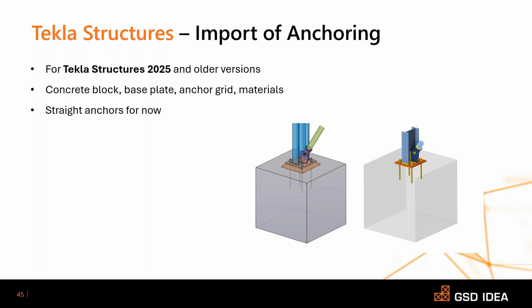Now with the base plate, you can also import the anchors and the concrete block from Tekla Structures directly into the checkbot. As of now, the limitation is that only straight anchors can be imported from Tekla Structures to the checkbot. However, other types of anchors might be available soon.